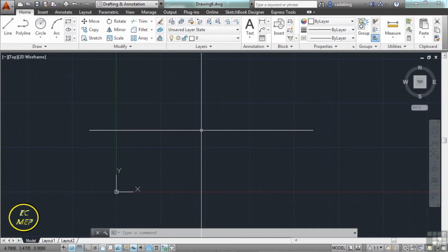So it's a relative thing. You'll have to pay close attention to your coordinates in this case. When you snap, you are snapping to a defined grid. That grid can be made either visible or invisible with a grid feature. It's a toggle, so you can turn it off or on by pressing the F7 key. Grid off or grid on.